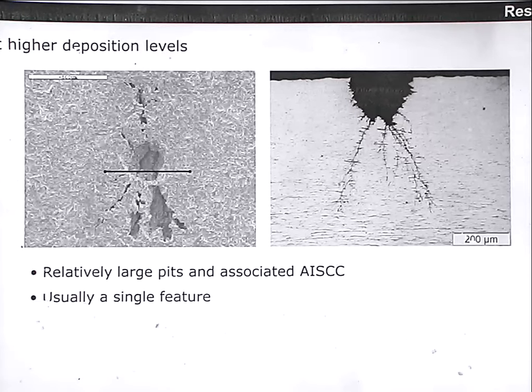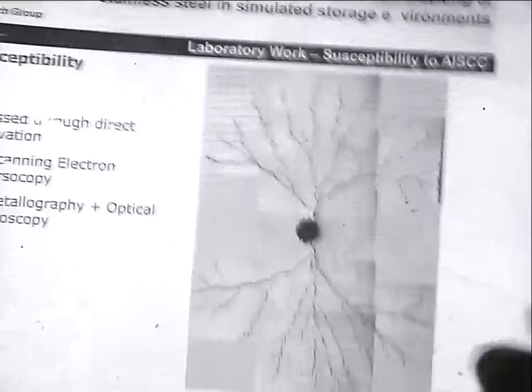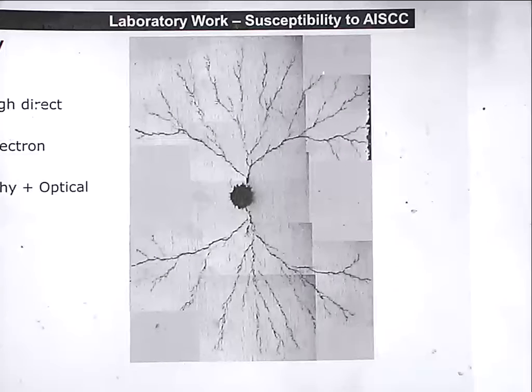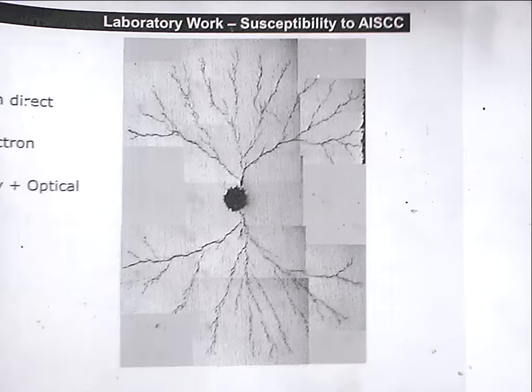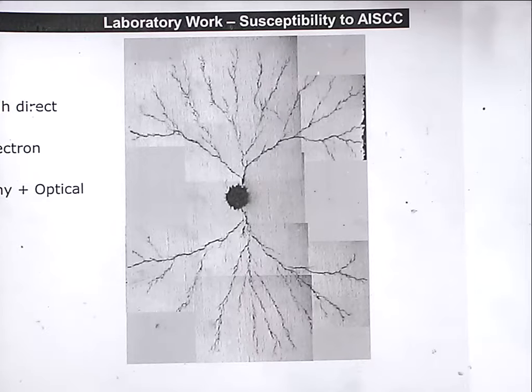And I suppose I might add, we mentioned, I think last time briefly, the two types of cracking. So you get transgranular cracking and intergranular cracking. This branching effect that you get and the slight kinks in the crack are indicative that it's intergranular. Okay. I think that was the slide that you had at the end of last time. Just reminding you, transgranular and intergranular cracking of materials.